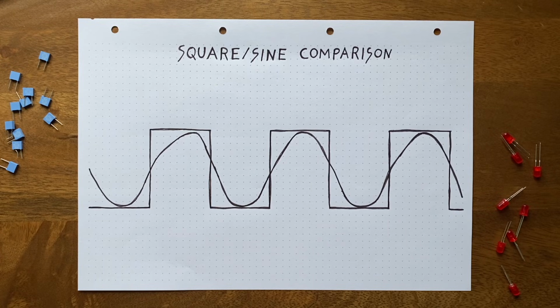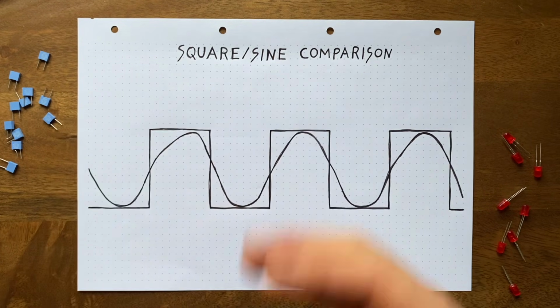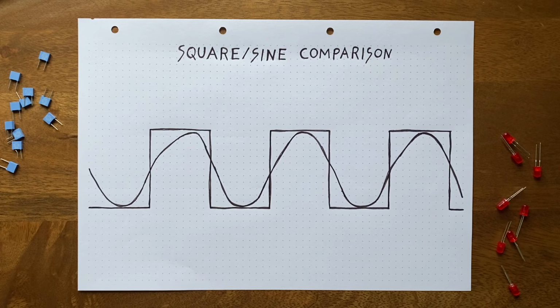And this leads us to a very basic definition of what filtering is in a visual sense. It's all about changing the shape of a given waveform. So while low-pass filters kind of sand down the edges and round them out, high-pass filters will make them more pointy and sharp, if possible. There's more filter types out there, by the way, but for now we'll focus on these two.